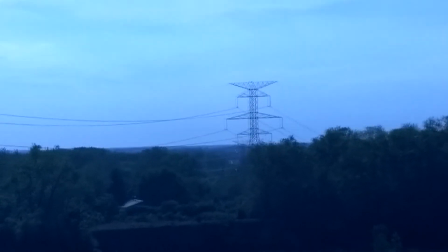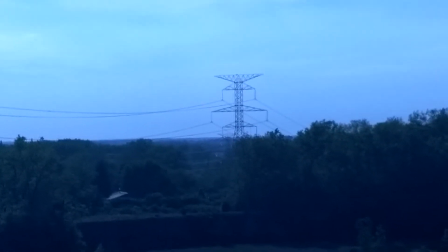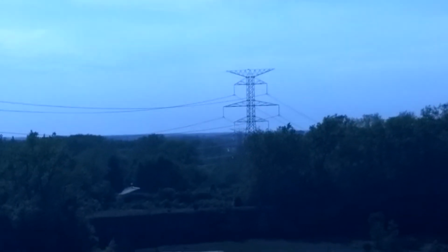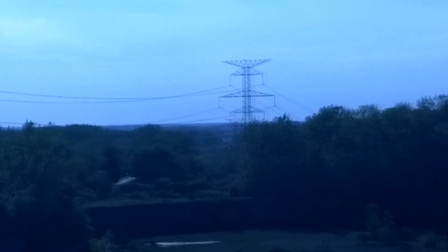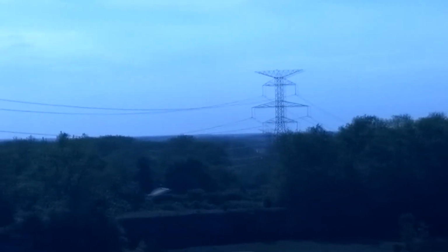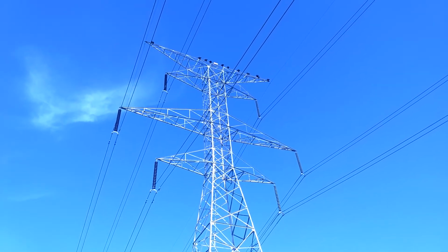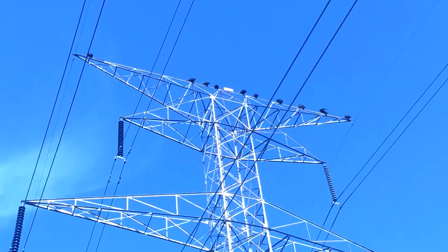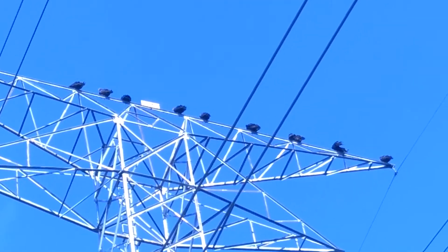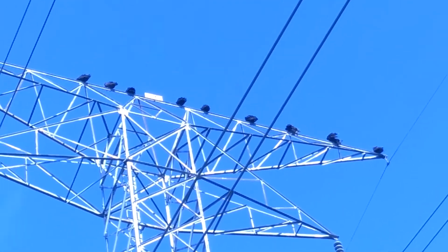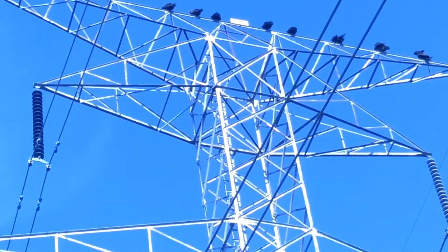That calculates out to about 400 amps that will flow through this capacitance between the wires for each 100 kilometers of length. And that can add up to a lot of current over the typical lengths of power lines like these. To give you a rough idea of the size of things up here, those birds are turkey vultures, which have a wingspan of up to 6 feet.